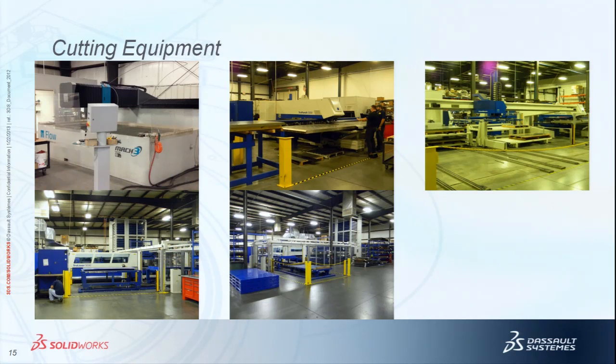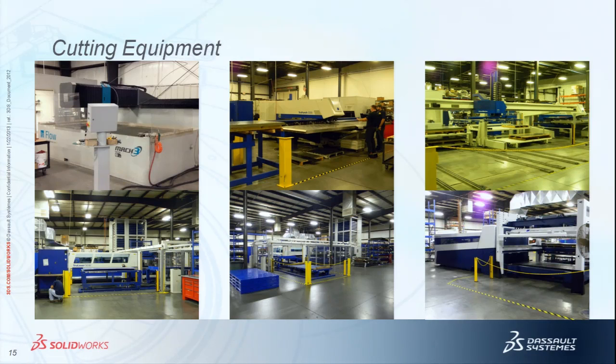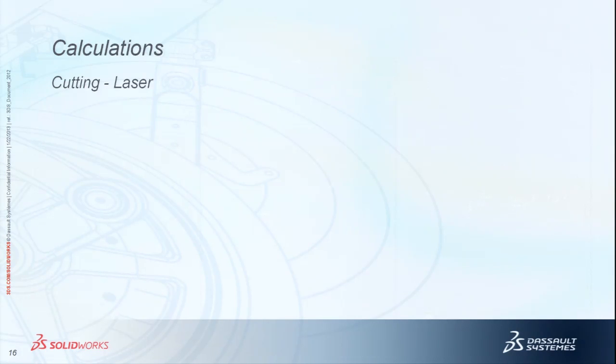We have a dual laser cell with an elevator that feeds them. That's fully automatic. You just let that one go. I wanted to account for that, but both of those lasers you can run with and without nitrogen. That changes the cost. And then we have a fiber laser that's fully automated, and that one runs screamingly fast. So I had a ton of variables here. I dropped it down. I went to punch, laser, and water jet. And water jet's just a really rough cost. I didn't work in all of the little details.